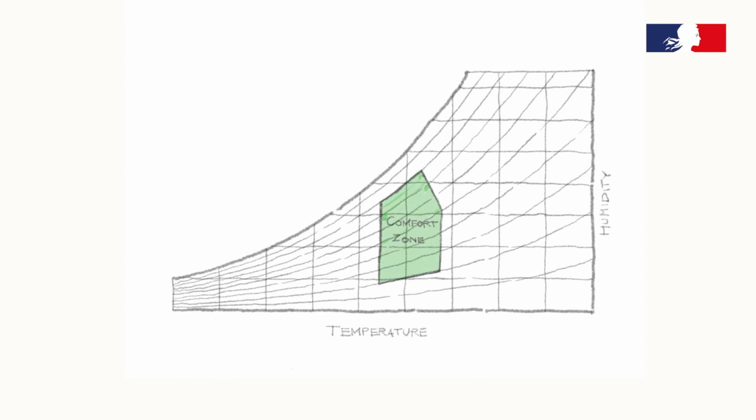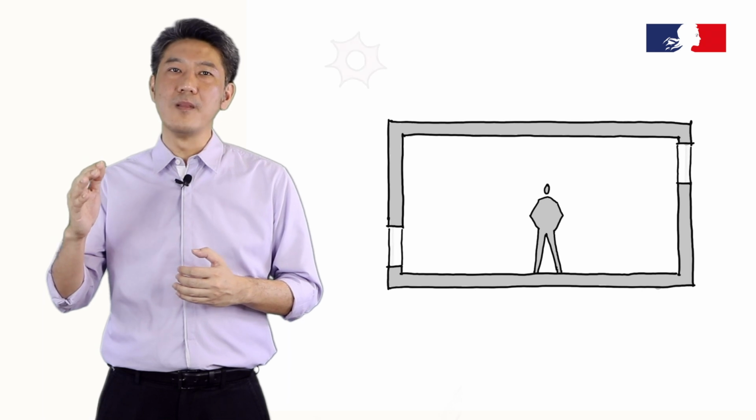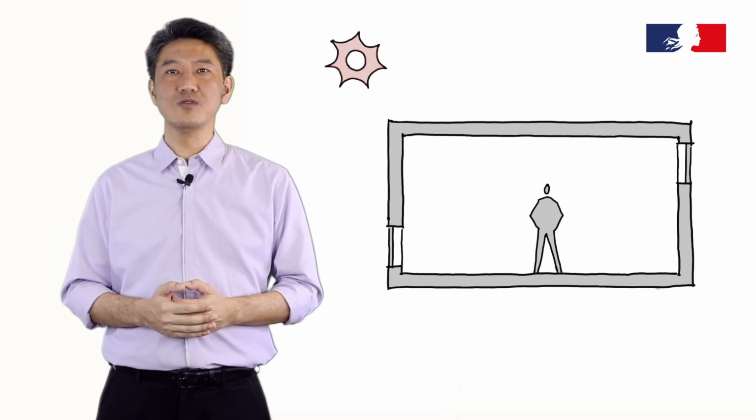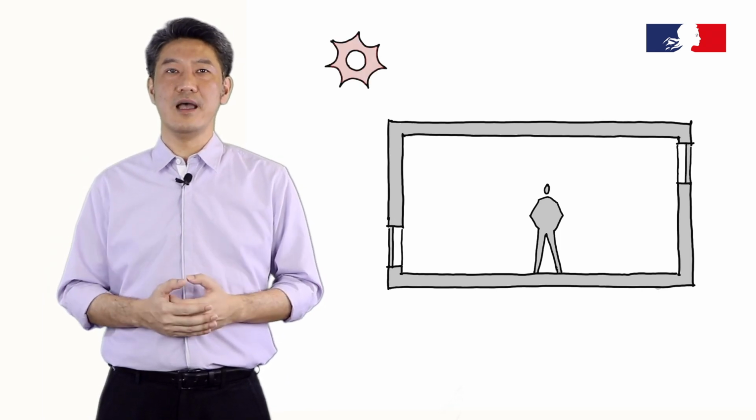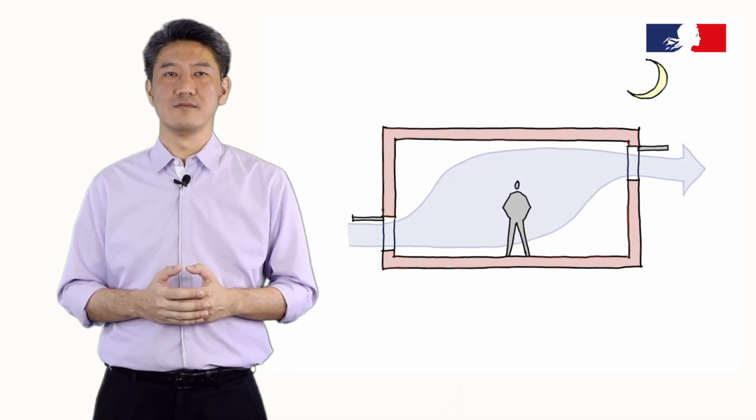The climates that are suitable for this method should have high diurnal change in ambient temperature. It is recommended for the climates with hot days and cool nights. The building should have small openings. During the daytime, when the air is too warm, the windows should be kept closed to keep the cool air inside. The windows should be open at night to allow nighttime ventilation.